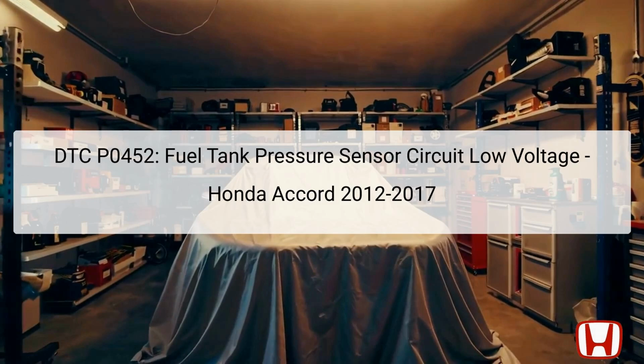This presentation is focused on diagnosing the DTC P0452, which indicates a low voltage issue in the fuel tank pressure (FTP) sensor circuit for the Honda Accord model years 2012 through 2017. The FTP sensor is crucial for monitoring the fuel tank pressure as part of the evaporative emission (EVAP) system. When the engine is running, the sensor detects the pressure within the fuel tank. Its readings are vital, as they help the Powertrain Control Module (PCM) identify any pressure leaks in the EVAP system.